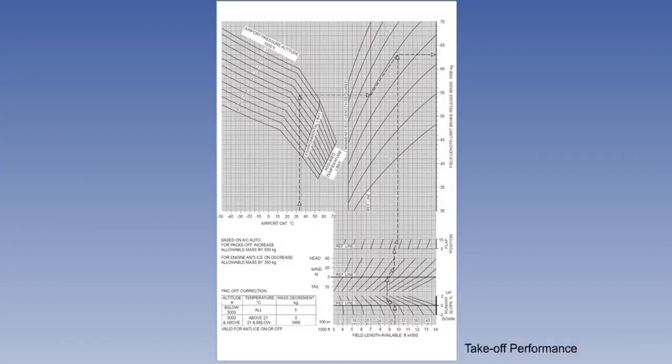For all takeoffs and landings, runway length is an important consideration. For takeoff, it is not just a question of whether there is enough runway to get airborne, but also whether there is enough to stop in the event of a rejected takeoff. For landing, there must be sufficient runway in which to brake safely. In both cases, deposits of water, snow, slush or ice on the runway will increase the distances required, either for the poorer acceleration due to the drag caused by the deposit, or for the loss of friction during deceleration.